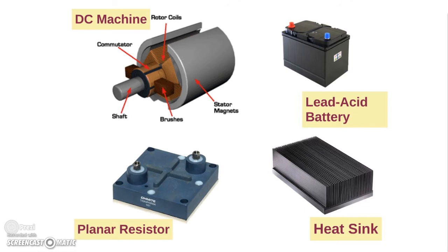The power electronic system operates under two modes, namely motoring and generating. In motoring mode, it is required to accelerate the motor, shaft, and turbine from rest to a predetermined speed. On the other hand, when in generating mode, it is responsible for maintaining constant shaft speed by applying a counter torque to the turbine shaft via the electrical machine.